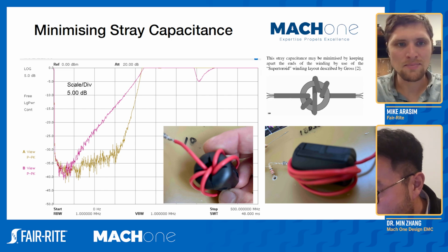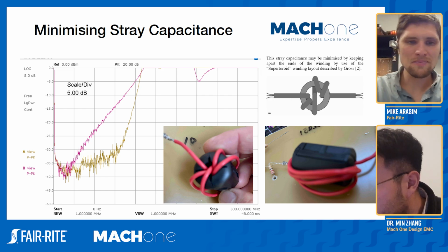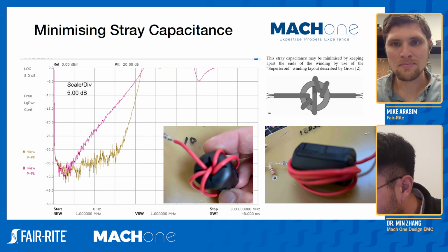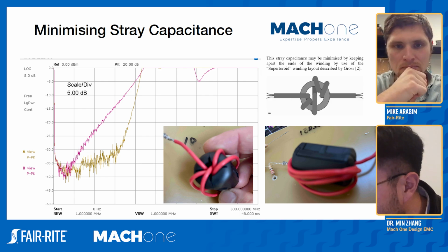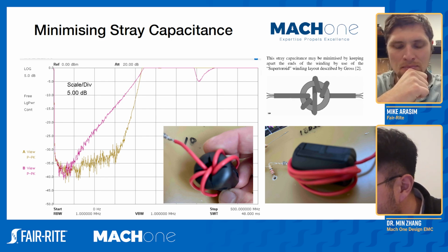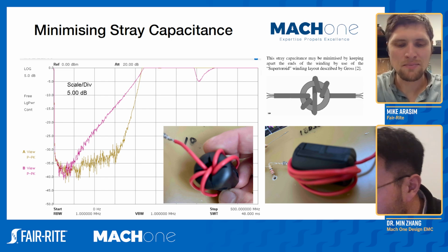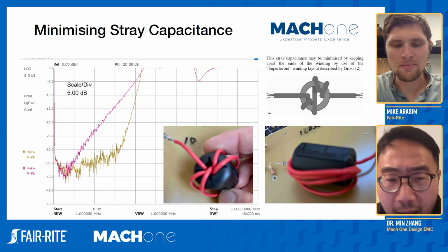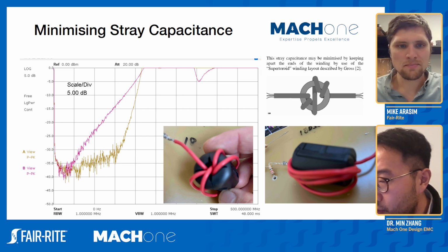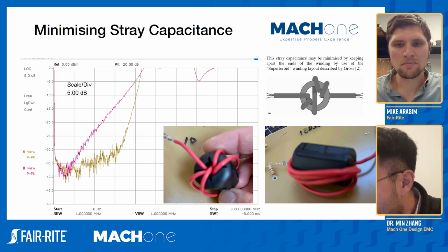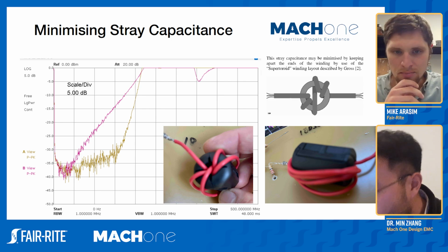as you said. And the reason is because of the parasitic capacitance as you introduce more turns. So in this case, I have to mention that it is a 5-turn configuration, so quite a lot. Therefore, you start to introduce the turn-to-turn capacitance. And these capacitors are quite small, but at higher frequency, hundreds of megahertz, now they started to make a difference. Hence, we see this peaky kind of performance.